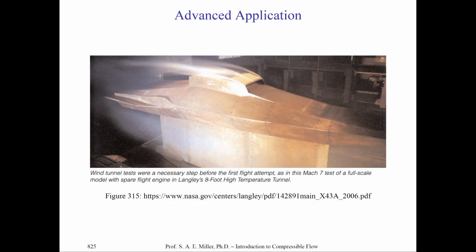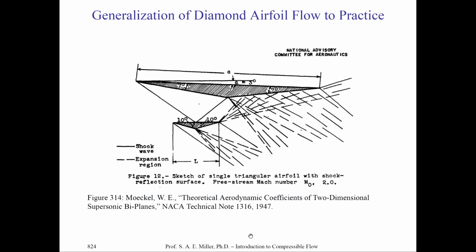Indeed, this is a hypersonic test at Mach 7 of a full-scale model from NASA Langley's 8-foot High-Temperature Tunnel. You can read more about this particular test at the following web address for the so-called X-43A hypersonic test vehicle. The X-43A was, of course, an X-plane, a test vehicle developed by NASA to understand high-speed combustion hypersonic tests with no moving parts, based on the beautiful theories of shock expansions.